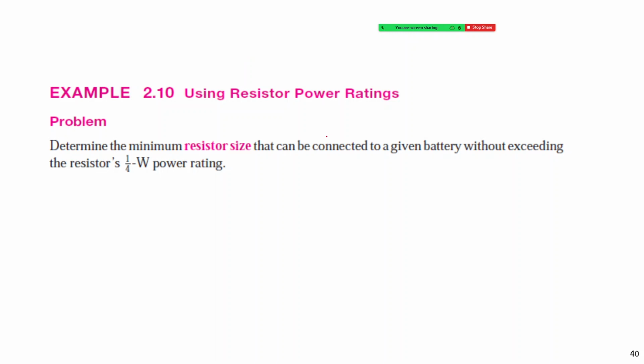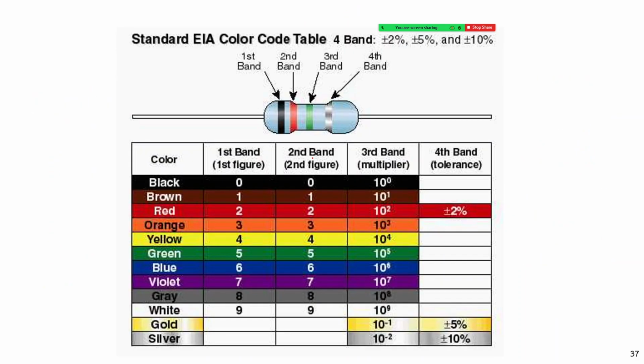Here, this example is to compute the resistor size or rating. Each resistor, for example, this type of element, it can be used for maximum power, right? The P, with P equal to V into I. This is the rated power. It has the limited rated power. If you use it higher than its rated, it will heat and it will burn out the resistor here, right?